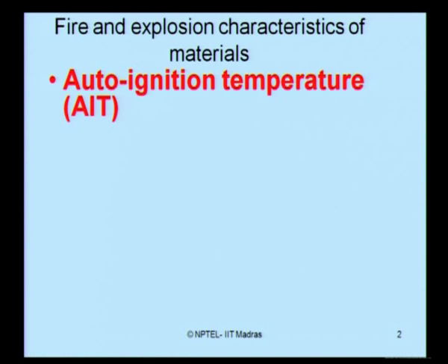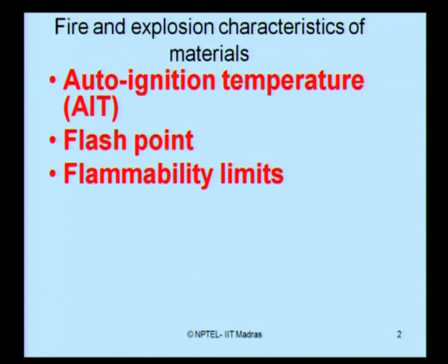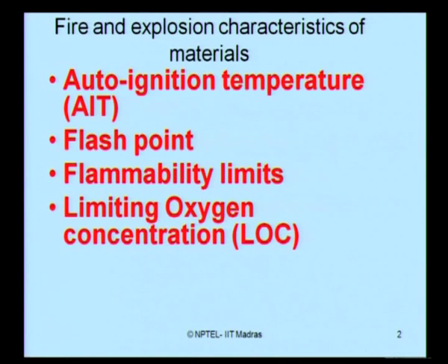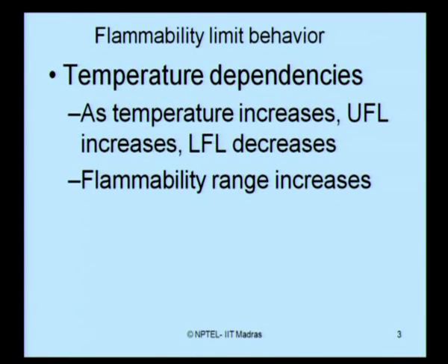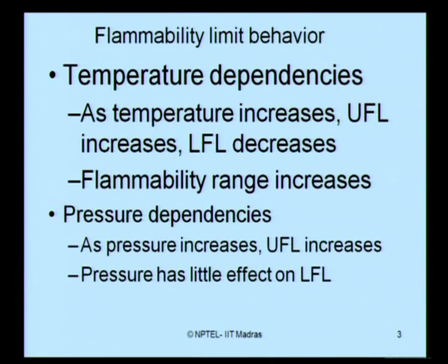explosion modeling. We have understood what is an auto ignition temperature, what is a flash point, what are flammability limits for a given material or a mixture, and what we understand by limiting oxygen concentration. We have also understood the flammability limits behavior, which is temperature dependent and pressure dependent. We have seen that as temperature increases, upper flammable limit increases, whereas lower flammability limit decreases. On the other hand, we can say very easily that the flammability range keeps on increasing with increase in temperature.